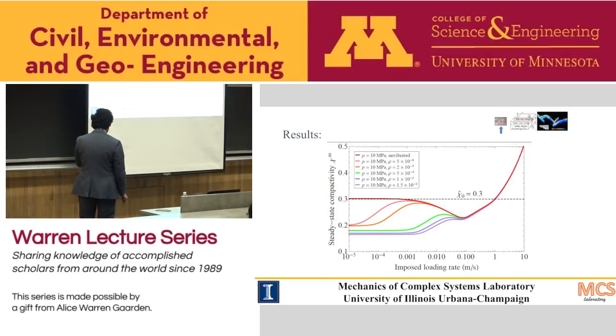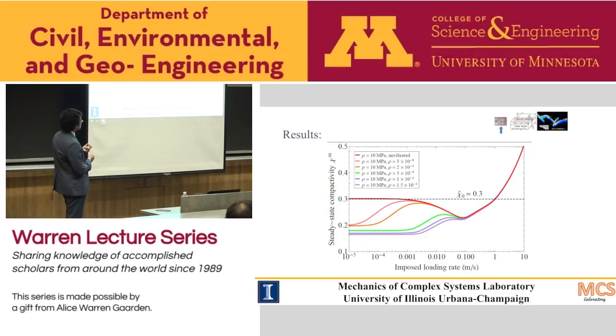So we know that we can have vibration of different intensities. It's not only a single intensity. So if we play with our theory and predict the behavior for different vibration intensities, this is no vibration, just the frictional grains being sheared. So you have this dip, and then you have a dilation. Now, if you have a given vibration intensity, then you start with a more compacted case. You increase the vibration intensity, you start with a more and more compacted case. Eventually, of course, you cannot compact the material beyond a certain level. So these curves here converge, but the interesting thing is, as you increase the vibration intensity, the non-monotonicity in the curve becomes diminished.